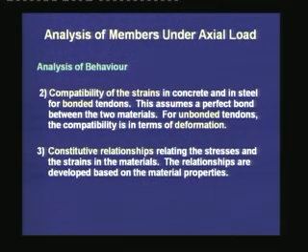For unbonded tendons, the compatibility cannot be expressed in terms of strain, but it can be expressed in terms of overall deformation. Now, in this lecture, we are not considering unbonded tendons, we are just studying bonded tendons, where we shall assume a strain compatibility between the concrete and the steel.